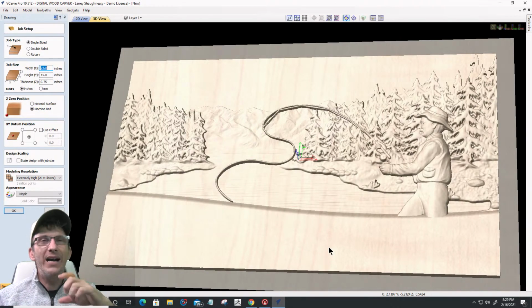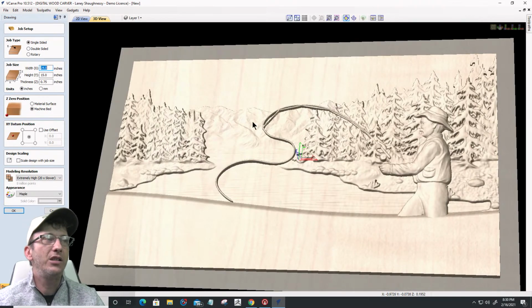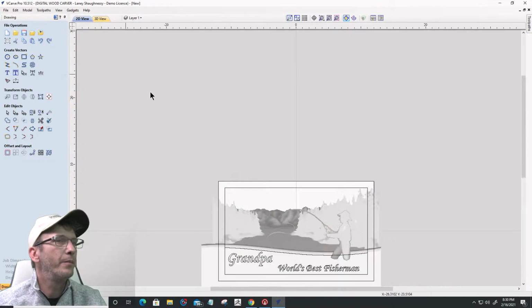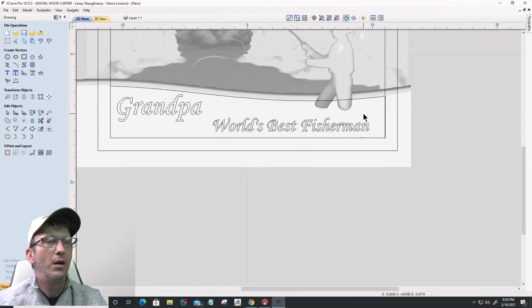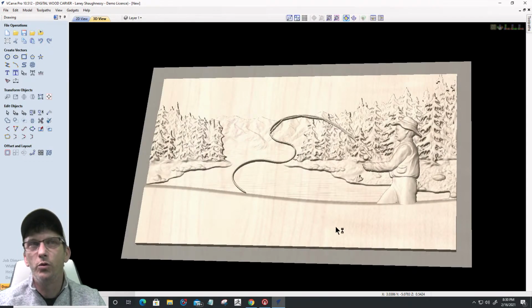I have to take my 3/4 inch board because my 0 is at the machine bed at the bottom of the board, right? So 3/4 is the top of my board in this scenario. So I've got to subtract 0.5424 from 3/4, and that'll give me my depth, how deep that is. So I've got to just simply come in here, I'm on my flat area here, 0.5424.